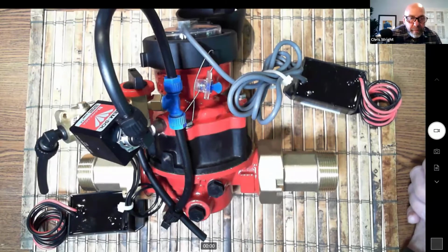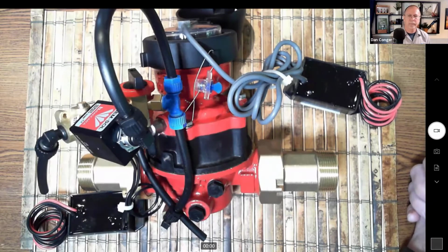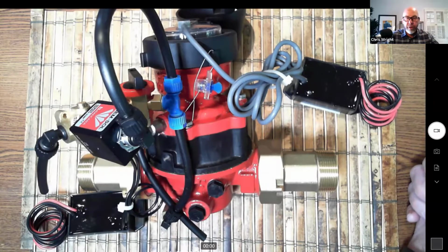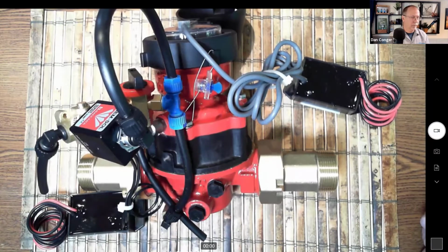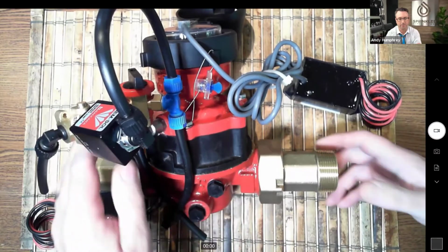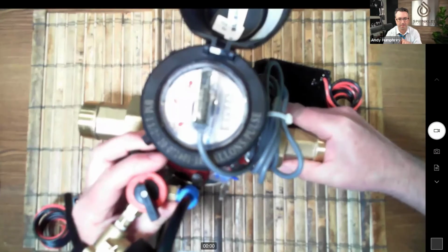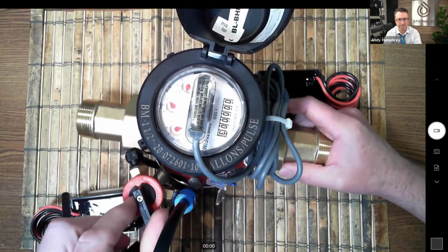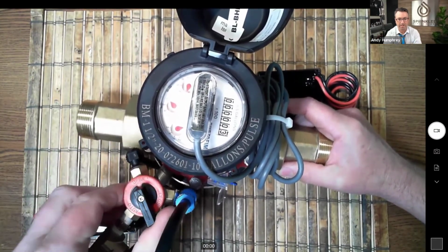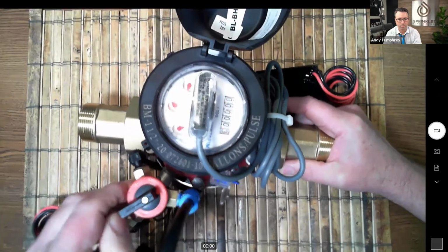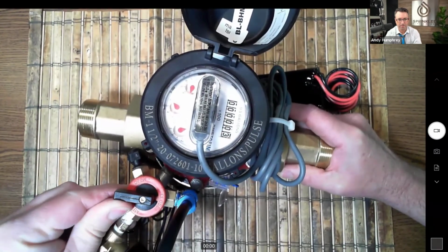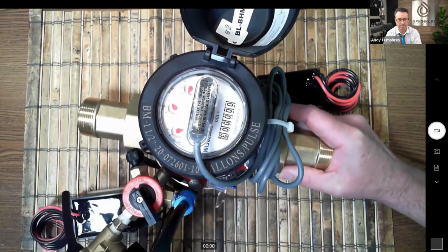Exactly. So it's always a good indicator if you open a box and don't know if it's normally open or normally closed: look at the tubing off the top of the solenoid to verify. And then Dan, can you rotate it a little bit and see if we can see the toggle switch that's on there? Because that's another important capability of the device. You can see there, and your camera's working well. I can actually read the words. It says open, close, and auto.